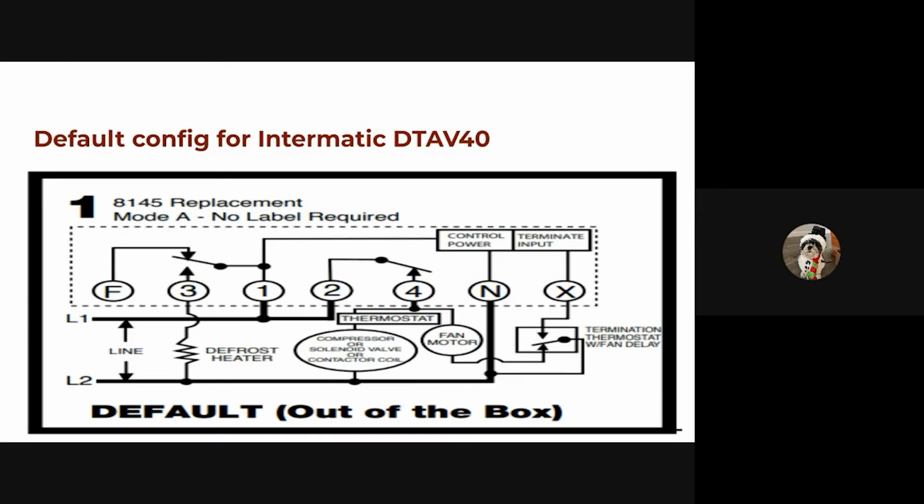You really wouldn't want to be doing that in a walk-in cooler, right? We just have defrost. We have these droplets of water on the evaporator. If you turn the fans on right away, you're going to push water out into the space. It may end up on the floor, and then you've got a slippery surface on the floor. So this will allow time for that to drip off.